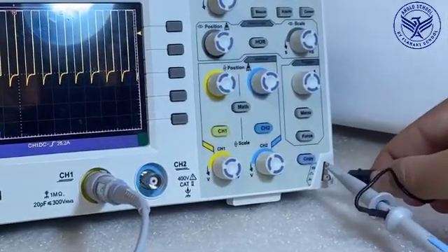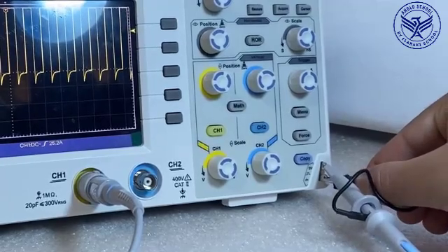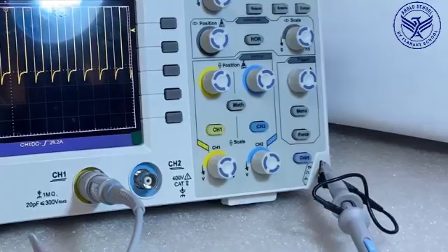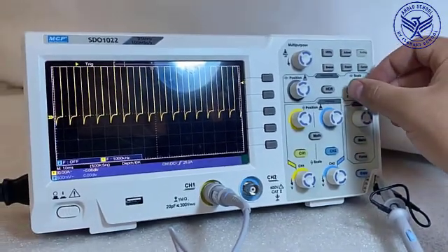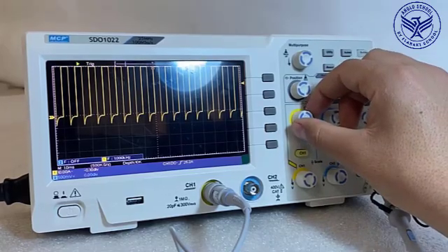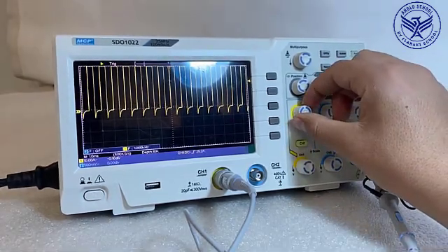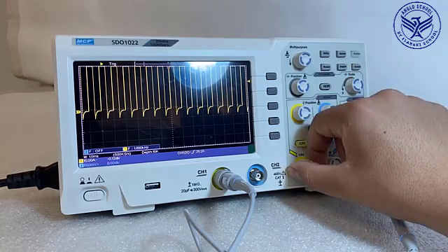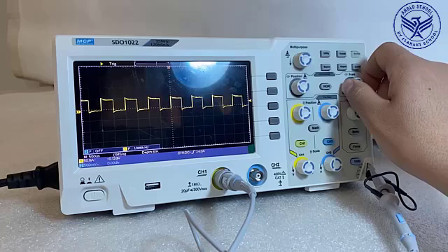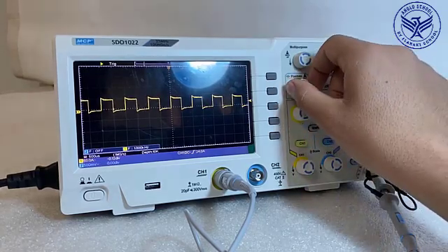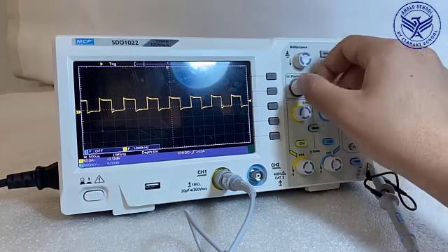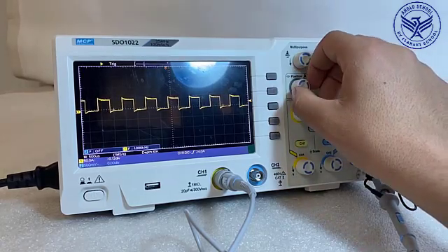Attach the ground clip to the ground tab and hook the probe around the signal tab. You should see something appear on the scope's display. Now, you'll need to adjust the horizontal and vertical scale knobs so you can clearly see the waveform. Note that turning the knobs clockwise decreases the time or voltage scale, which has the effect of zooming in on the waveform. If you want to move the waveform up or down, you can adjust the smaller knob above the channel 1 button. Just note that this moves the 0 volt level for channel 1 as well.